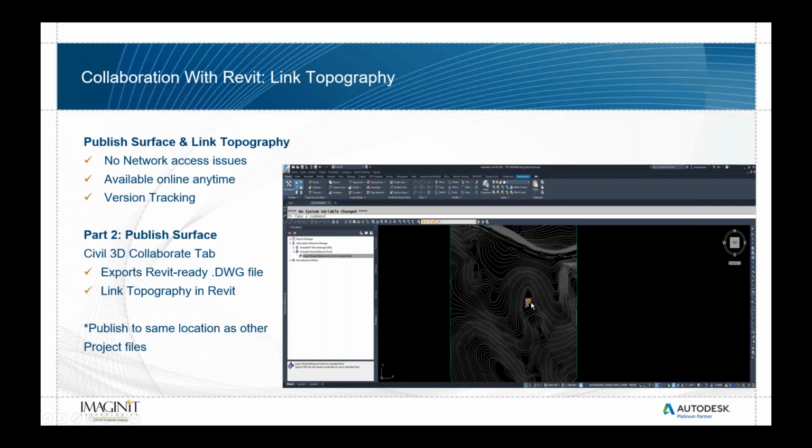And to get the Revit drawing into Civil 3D, it was basically just export AutoCAD. There's an option to export AutoCAD from Revit. It gives you a 2D AutoCAD file of the building footprint, and then you can XREF that into Civil 3D. If you needed a 3D version of the Revit file, you go to 3D view from Revit and export it out, and you get a 3D AutoCAD block of the Revit drawing there too.